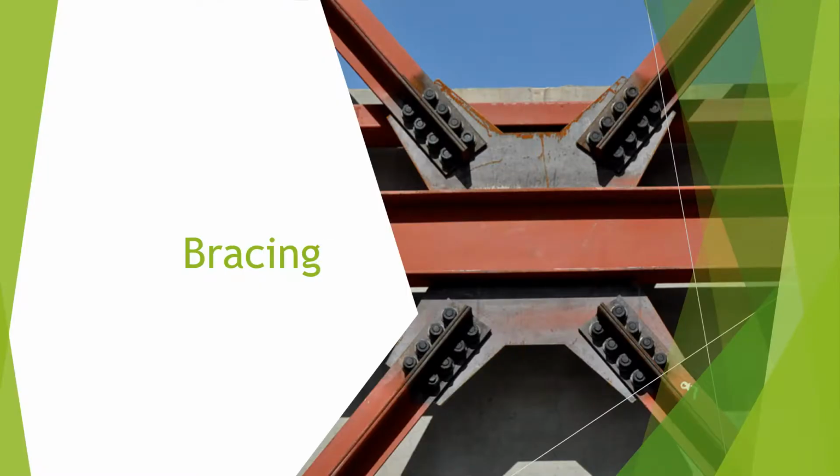So have a look at this picture here. What do you see besides that beam there? Right, angles. So here's our angles at work. They serve as a bracing to stiffen the steel structure when they're used as bracing in this manner. The two pieces of angle iron back to back, if you have a look there, they're bolted together in the picture. So they're assembled so that they serve as a bracing. And there's a connection plate there where those bracing sit. It holds the bracing in place